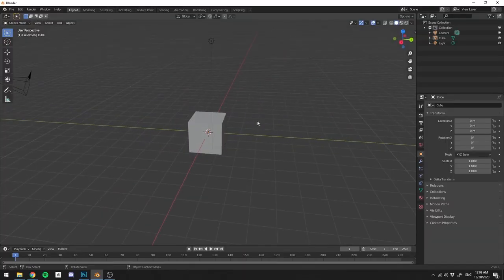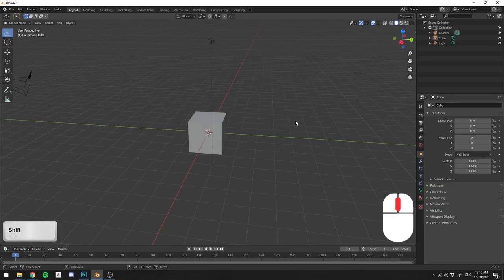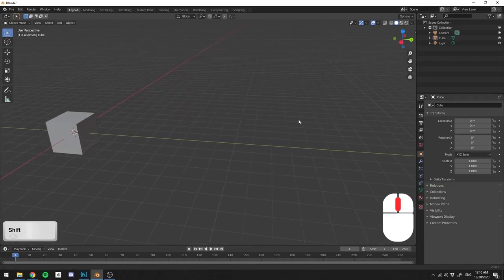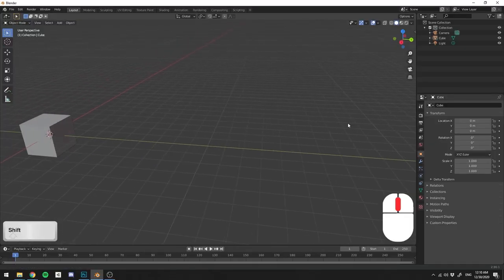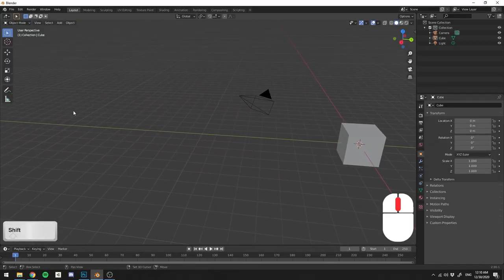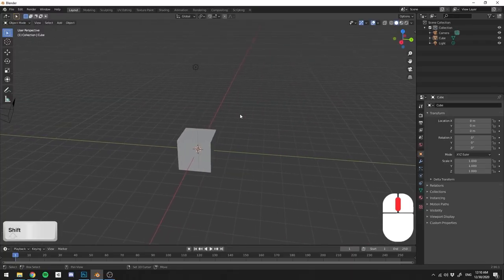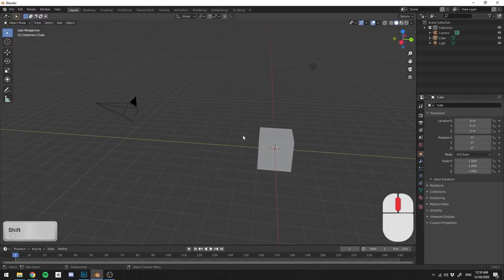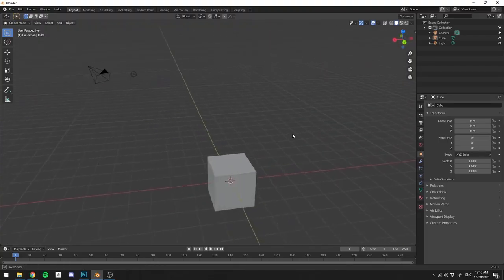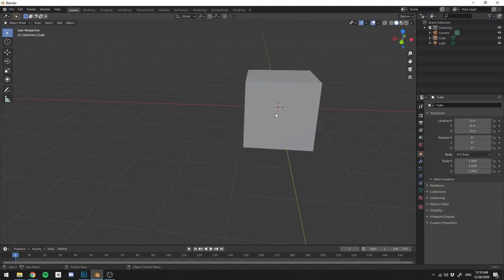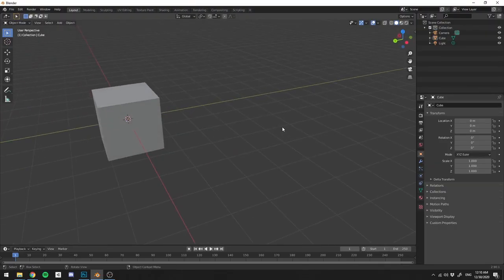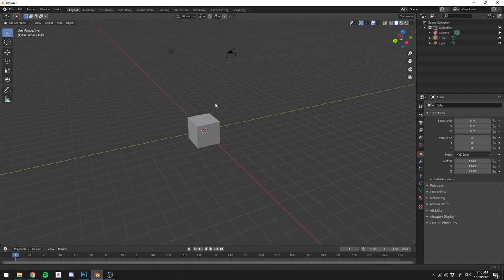And the last thing that you need to know is how to pan, how to move away from that cube. So how to do this? Hold Shift on your keyboard, and again with the middle mouse button pressed, start to move away from the cube. Just press it and drag your mouse away from the cube. As you can see, you can pan with it. And if you start combining all the keys that I've told you about, let's say I rotate, I pan a little bit, I zoom, I pan, I rotate. So those are the Blender hotkeys.